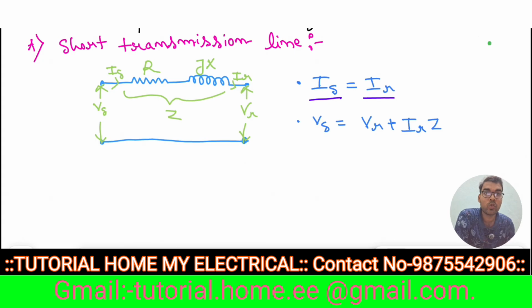Now you have to know the circuit parameters, means ABCD parameters, of the short transmission line. For calculating the ABCD parameters, we have to draw the circuit of the short transmission line. In a short transmission line, the sending end current Is flows through a resistance and inductance, and we get the receiving end current. So the sending end current is equal to the receiving current.